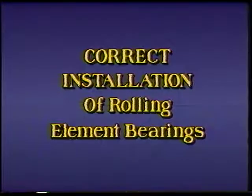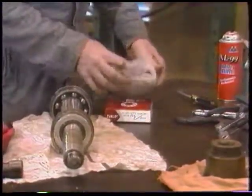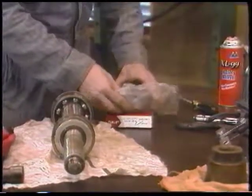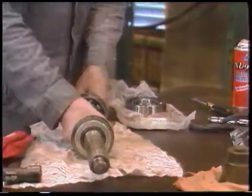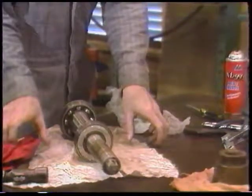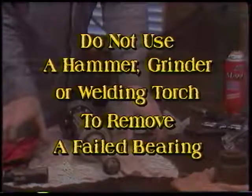Like plain bearings, rolling element bearings must not be distorted during installation. Both rings must be firmly supported by a perfectly round bore and shaft. This means that when you remove a failed bearing for a replacement, you must be careful not to damage the bore or shaft in any way. Removing a failed bearing is often difficult.